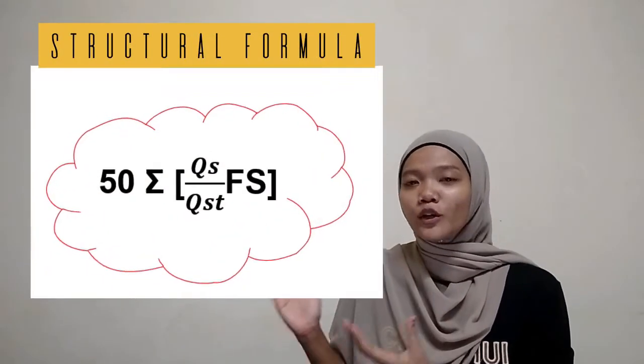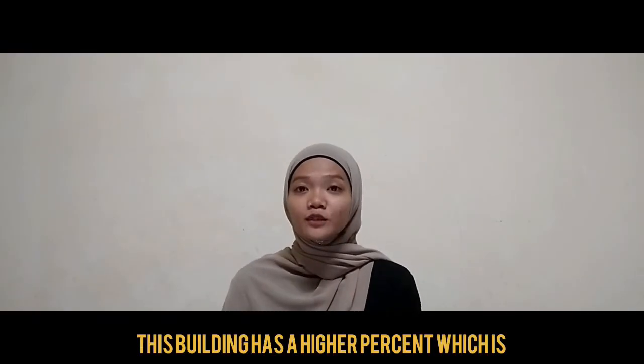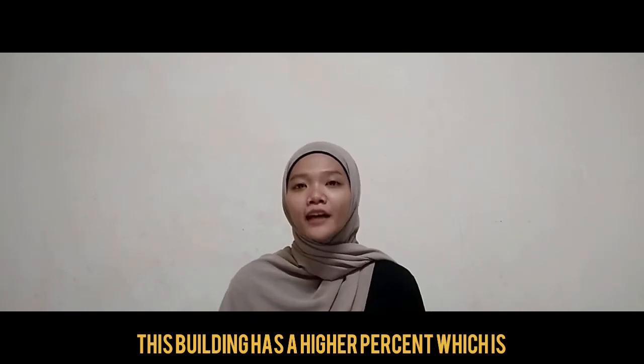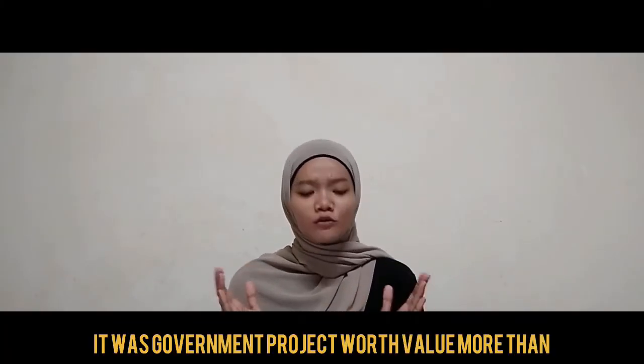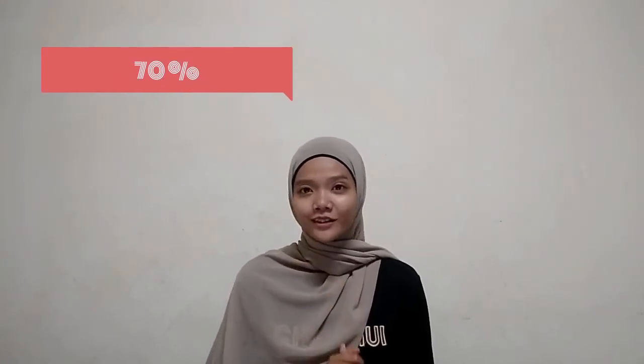This is the formula of the structural system that we use to calculate the IBS score, and this is the wall system that we use to calculate the IBS score. After we calculate the IBS score, this building has a higher percentage, which is 72.5%. So it is a government project worth more than 10 million because it has more than 70% IBS score.